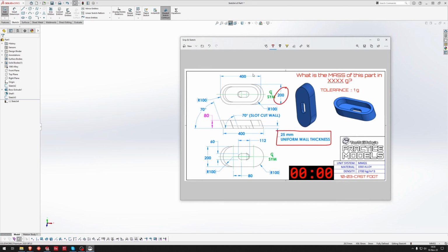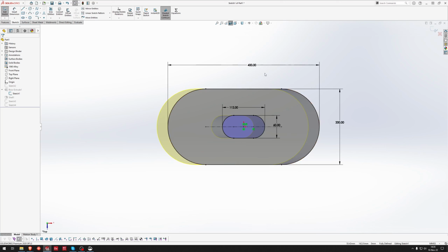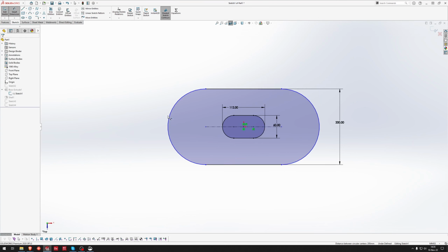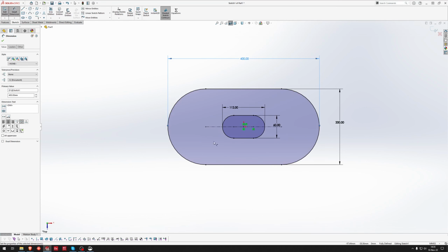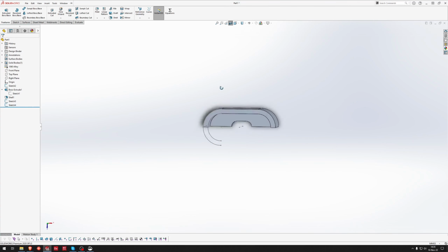This is pretty straightforward. To get these dimensions, in case you have never done that before, let's go ahead and pop into this initial sketch that we created, not that one. Edit sketch. So to get this dimension, if you select this circle or this arc and that arc, normally that goes between the center points. Quick tip that hopefully everybody already knows, holding down shift will let you go to the outside edges of the arc instead. So that's how I got those dimensions quickly. Again, I could have done a little bit faster on those, but regardless, that's how we get those squared away.